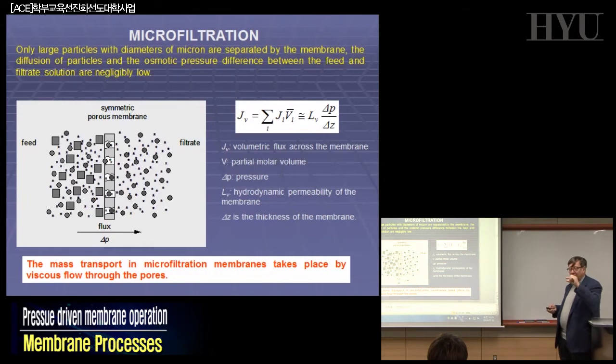One way of doing it is to increase the thickness of the membranes. You cannot increase too much, because you are also increasing the mass transfer resistance. But you have to find the optimum between the mass transfer resistance and the heat transfer resistance, because you want to reduce heat transfer in such a way that all the energy that you are supplying to the system will be utilized to evaporate the water and move across, and not warm the polymer. Warming the polymer is a loss of energy. Today, about 50% of the energy we supply in membrane distillation is lost by thermal conduction across the polymer, which we don't want.